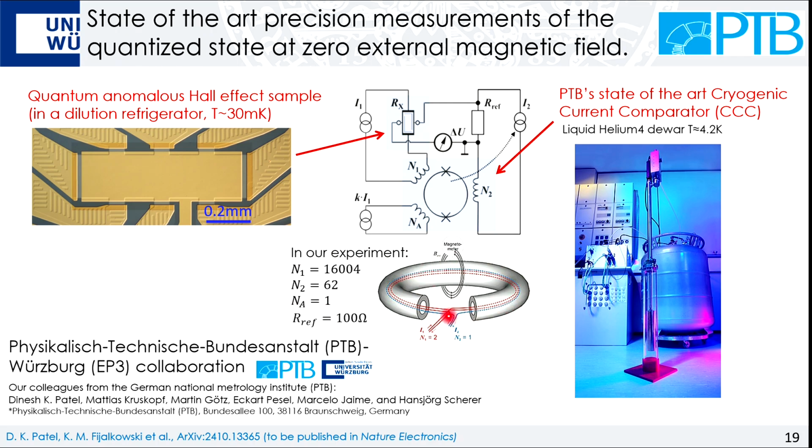And the way this is done, these two wires run inside of a superconducting shield. The two currents you want to compare flow in opposite directions inside of this shield. The difference between these two currents creates a magnetic flux. The magnetic flux creates a screening current on the superconductor. The screening current on the superconductor again creates magnetic flux, and this is picked up by a DC SQUID. So a SQUID acts as a null detector to adjust one of the power supplies to balance the current properly. Again, if you're curious about more details, you can look up this arXiv paper we put up recently.